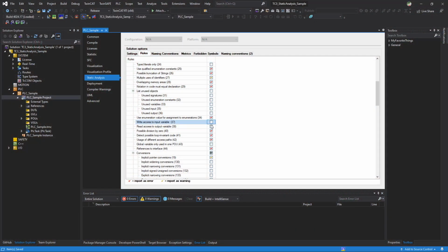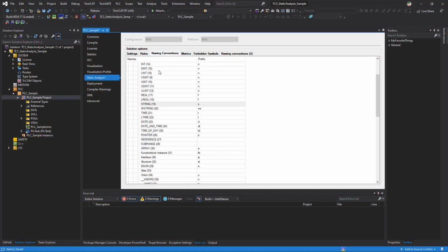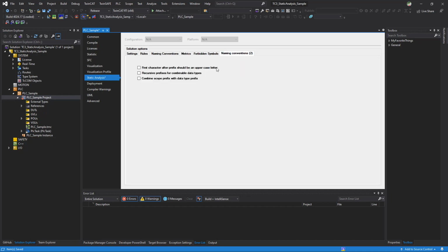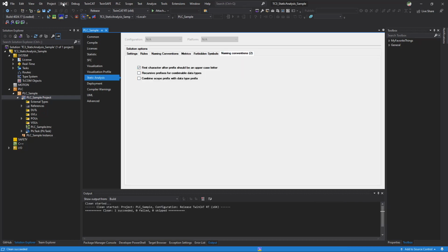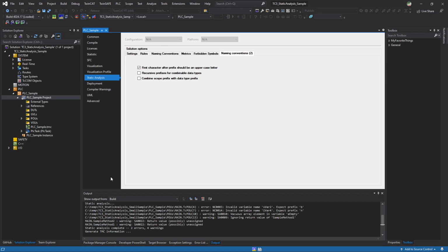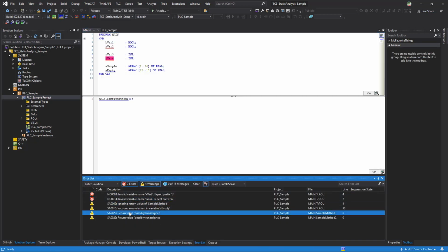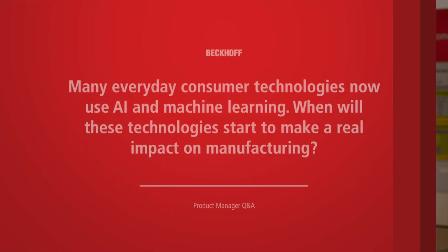So if you have multiple programmers working on a team on the same machine or even on different machines within the same company, we want to keep the coding very consistent. And with static analysis, we can set up rules, say, hey, you must name things like this, you're forbidden to use certain keywords, things that are not returning correct codes, flag a warning or an error, really filling out the professional software development suite. So the TwinCAT environment is really trying to help do a great job of bringing all these things together and giving professional tools to help minimize that complexity.